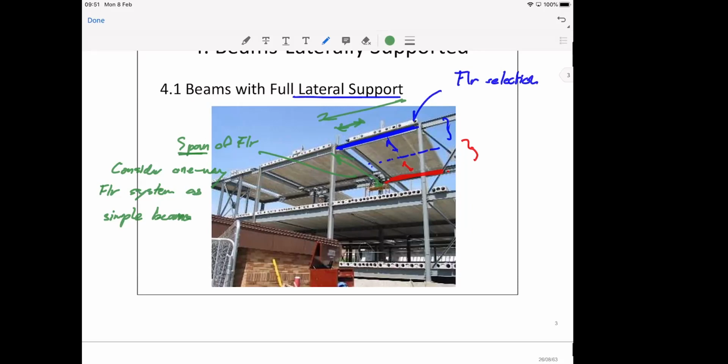No. So generally, when you use this kind of floor, we need to find a way to connect the floor to the beam that you use. In turn, this floor, which is carried by the beam, will also help brace the beam from having any movement.